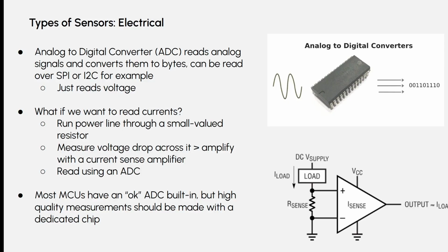You basically use an amplifier, an op amp, which you will probably cover in courses, but it basically just significantly increases the amplitude of the signal. So if it previously went from 0 to 1 millivolt, crank it up 1,000 times, and it'll now go from 0 to 1 volt. Then you can read that using the ADC and just do the math on the resistance value. That's the proper way to measure current, and those are both things we do in our system to monitor the power.